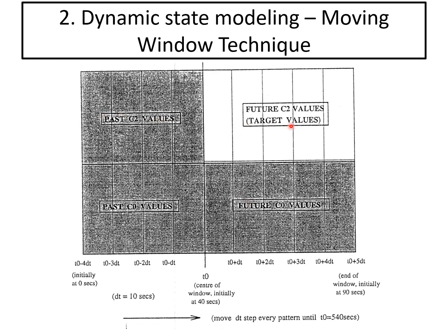But since we want the future C2 values, we also need to put in the future C0 values, which can be done if in simulation we know what future U we want to use. So we can put it inside the network and then get the prediction of the output for k plus 1, k plus 2, and the future times. This is what we call the moving window technique strategy. As we go along the data set, we will get the future data as predicted.